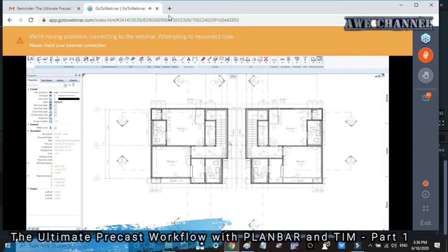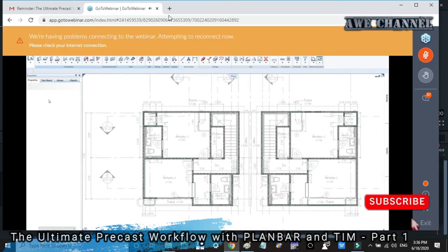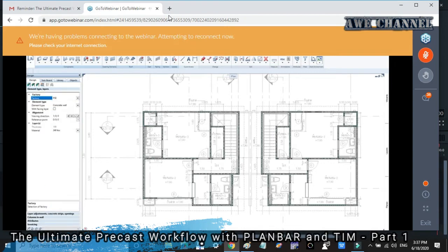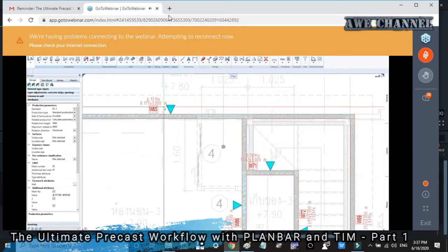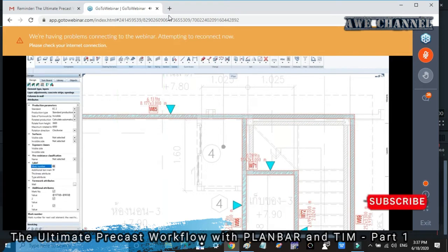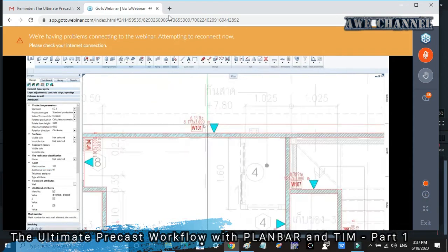Okay, let's say I have done the precast wall, and now I want to make precast wall elements. I just go to design again, and from the design, I have to select precast, architecture wall. In a few seconds, you will get precast wall elements. And you can modify mark number. If you want to start the first mark number from 101, you just change the label mark number to 101. And then the first wall will start from 101.